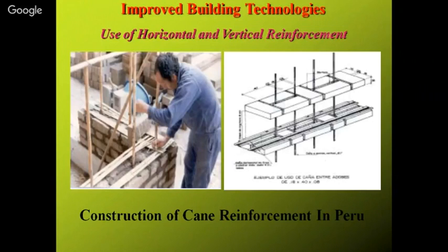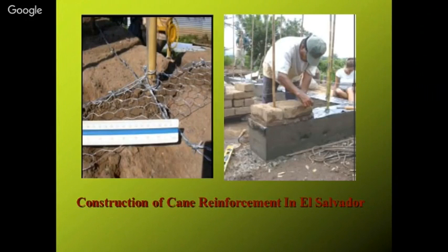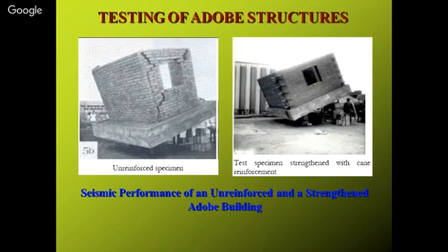These are very, very small things which we need to incorporate in our house, and our house will be earthquake resistant. In some rural areas, chicken wire mesh can be provided in place of reinforcement bars, if you do not have them. Chicken wire mesh can also be provided as horizontal bands. These are some pictures of the test. I'll show the real shake table testing of a structure.